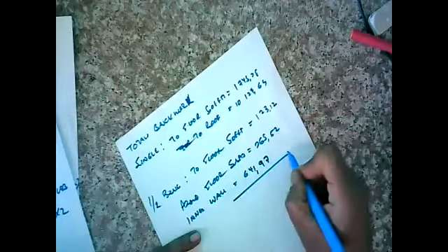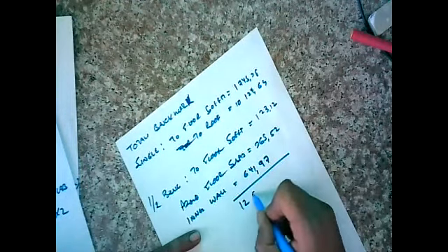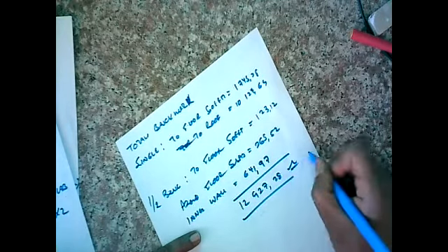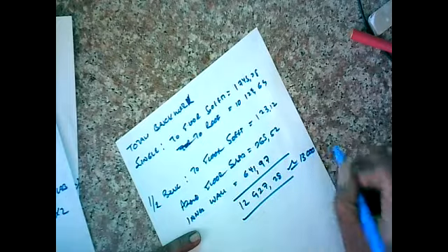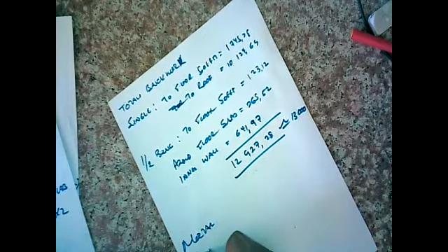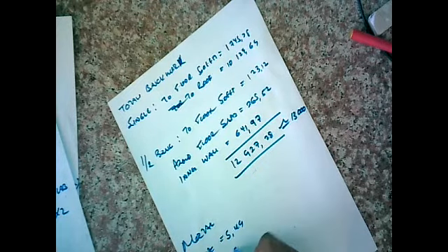All right, and if we tally all that, I'm getting a value of 12,927.28 bricks, which we will round up to the next 100. Our mortar, simple one, single, we came up with 5.49, and with our half, we found it is now 0.34, and our total mortar is 5.83.